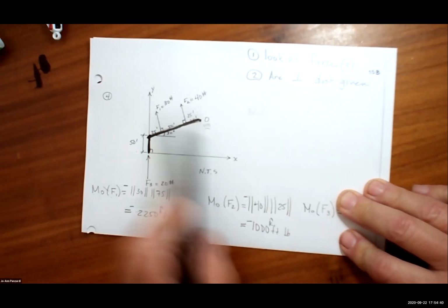But now we know dot product in and out everywhere. Here's a distance, we have an angle. I thought we wanted that opposite distance, didn't we? Because we wanted to know the perpendicular distance to O. Good, but take a look again. This is the force in green, right? Here's the force, here's the point at O. Isn't this the perpendicular distance? Oh, yeah, I see.